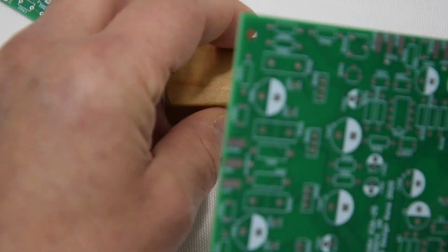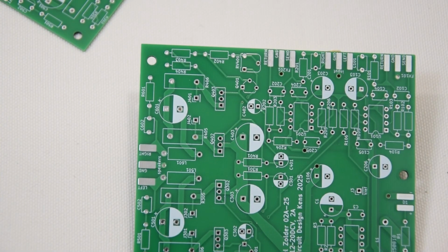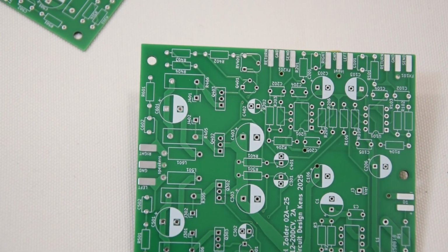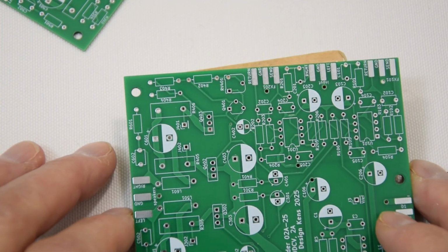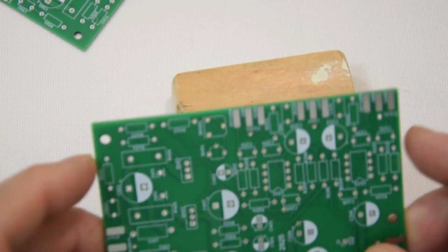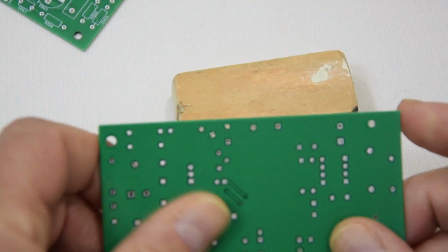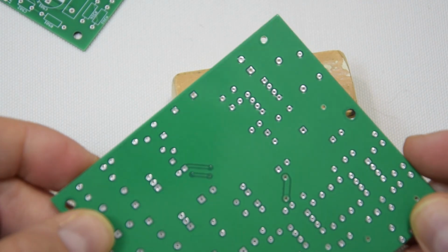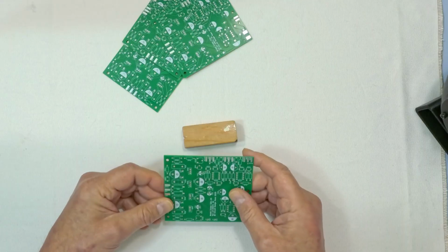Now you could try building this on a variboard or strip board and soldering everything by hand, but trust me, that's asking for trouble. I've been down that road and it's easy to make mistakes. Low-level signals are hard to isolate from power traces, and it will lead to crosstalk and distortion. Plus, without masking of the traces, leftover flux or tiny solder particles can cause unwanted currents and noise. So, in the long run, you will be better off with a printed circuit board.